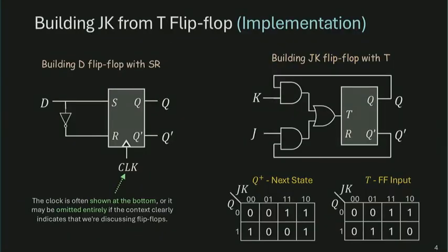All right. Now let's actually use this flip-flop to build something, which is like a tiny implementation practice. We can build a D flip-flop from an SR flip-flop, just like what we did with the SR latch and D latch. We can use a single input to control both S and R, but complement that input for R. So if D is 1, we're going to set it, so Q becomes 1. If D is 0, we'll reset it, so Q becomes 0. Right? Indeed, if you look at it from the input-output interface, D and Q, it works exactly like a D flip-flop.